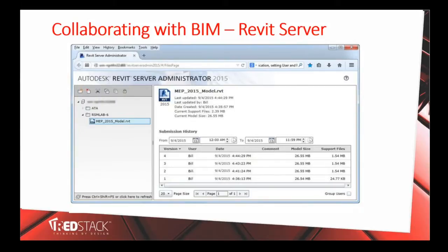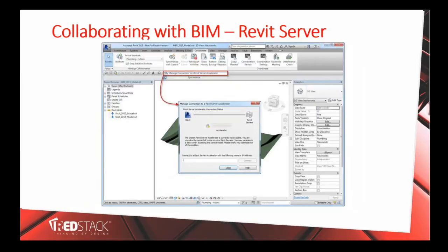It's crucial that you have underlying connectivity. When you set up your Revit Server, you have what's known as an RSN, or Revit Server Network, INI file. It's a text file stored on your systems, which lists all the names and IP addresses of all the hosts and accelerators within the network. This RSN INI file must live on the Revit Server for it to work effectively. Once the Revit Server is connected, each instance of Revit needs to be connected to that local server accelerator.